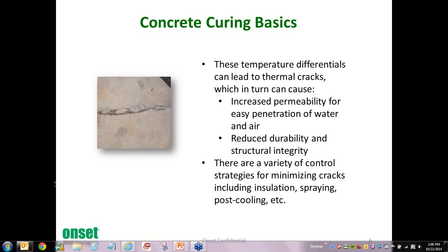The Portland Cement Association stipulates three main functions of curing. Firstly, you want to maintain the mixing water in the concrete during the early hardening process. Secondly, is to reduce the loss of mixing water from the surface of the concrete. And lastly, you want to accelerate the strength gain using heat and additional moisture.